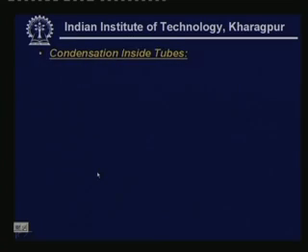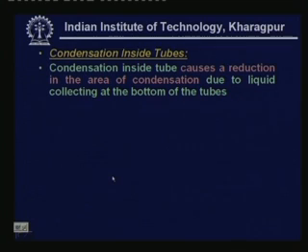Now, let us look at condensation inside tubes. This is actually more complicated compared to condensation outside the tubes or outside the surface. This is because condensation inside a tube causes a reduction in the area of condensation due to liquid collecting at the bottom of the tubes.